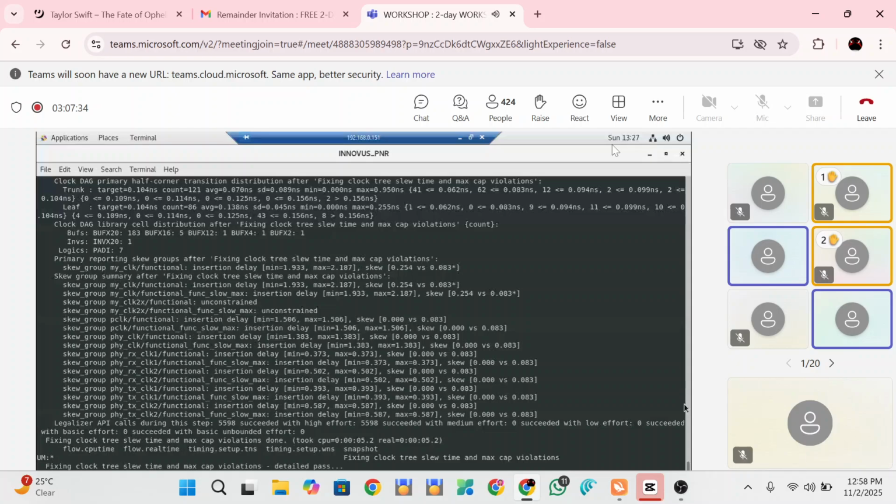So alternate layers will have a vertical and horizontal format to make accessibility easier for connecting. Each layer will be connected to the other layer, so to connect from one layer to the other layer, let's say M1 to M2, that connection will be made via a via. It is like a pillar between one metal and the other. Like construction slabs, they are connected one to the other, from one floor to the other floor. That is how the connection will be. Okay, now it is there.